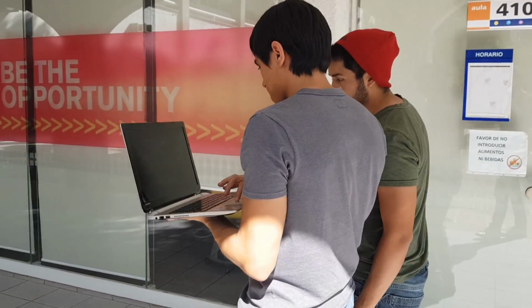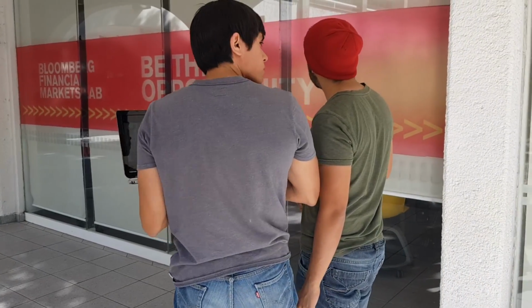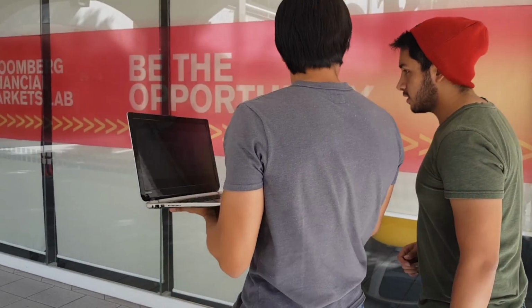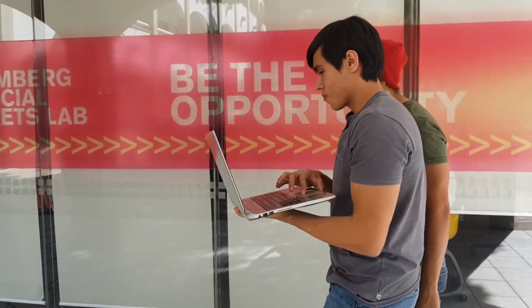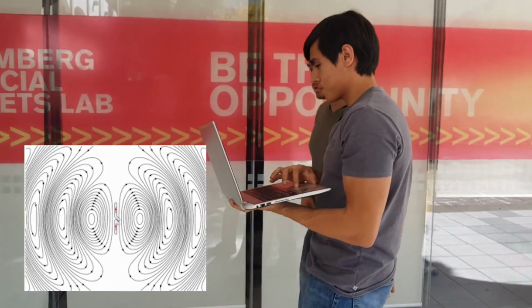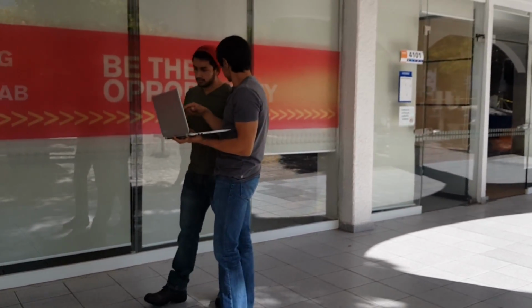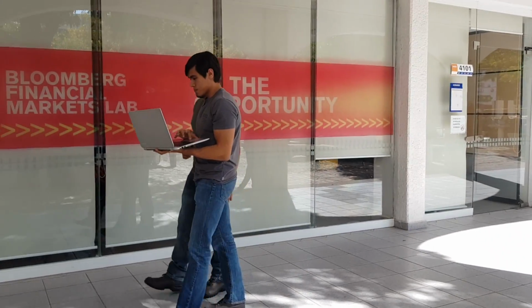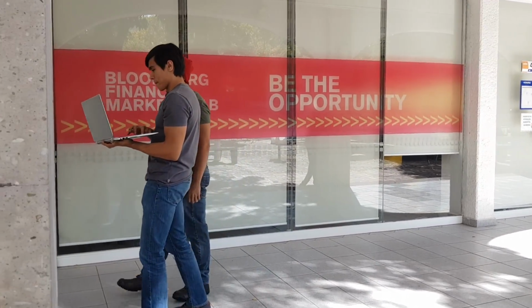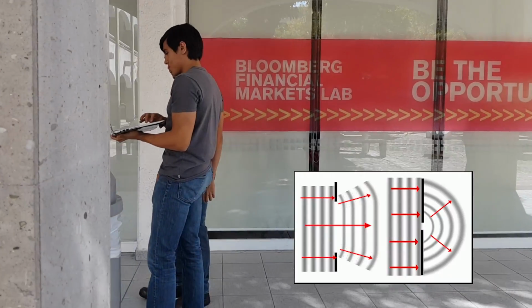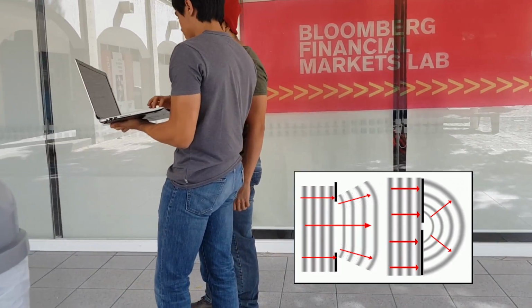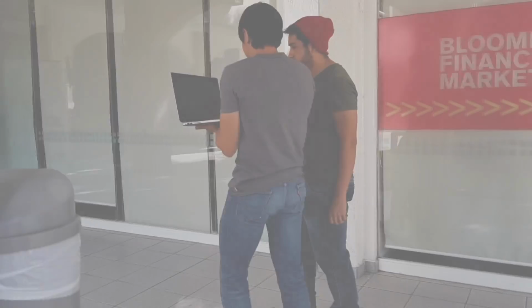To improve the signal in the marketing room, it is necessary to define if we want to have an omnidirectional antenna or a directional antenna. The omnidirectional antenna has more benefits for this area, because it is an open space and does not need a specific target. The glass in the cars helps the Wi-Fi not to lose too much power, and the sharp edges of the walls help to diffract the signal to more spaces.